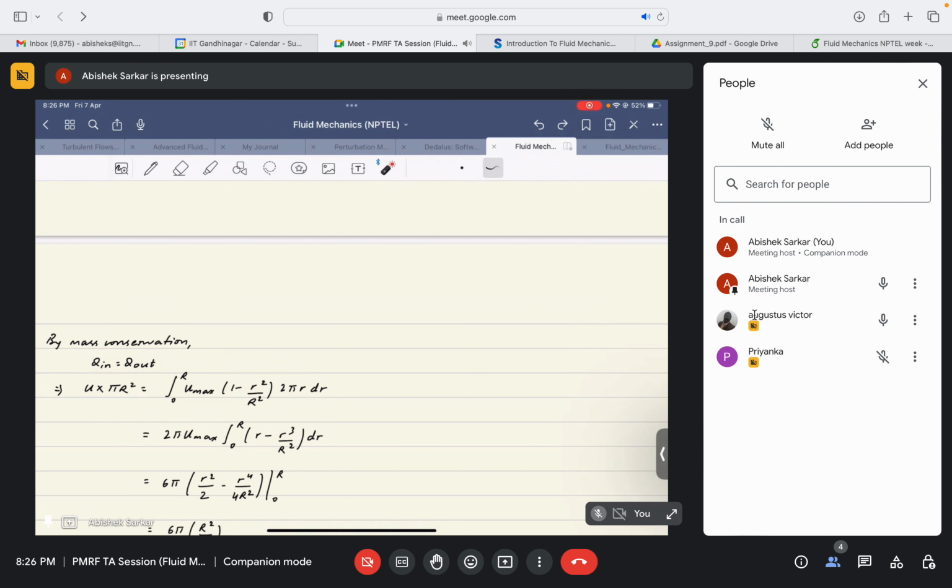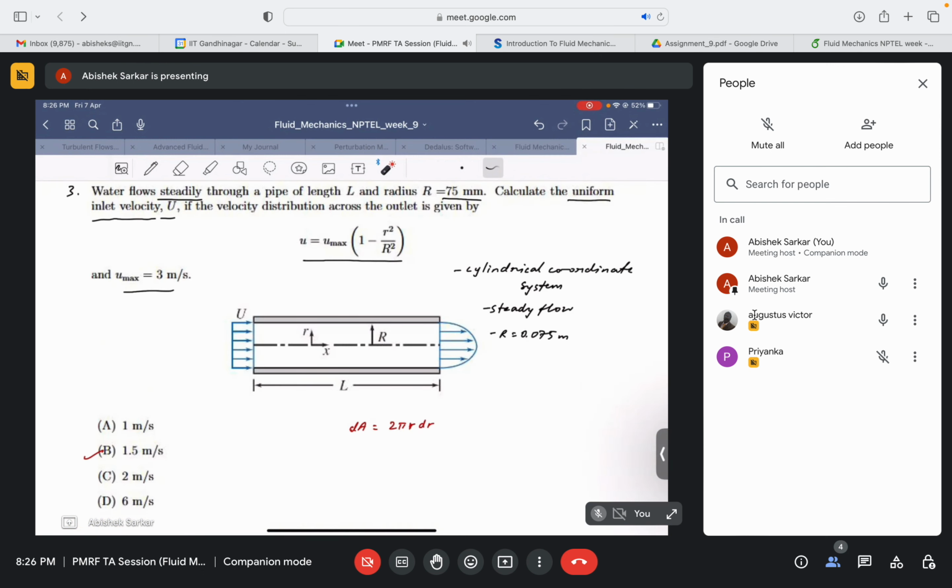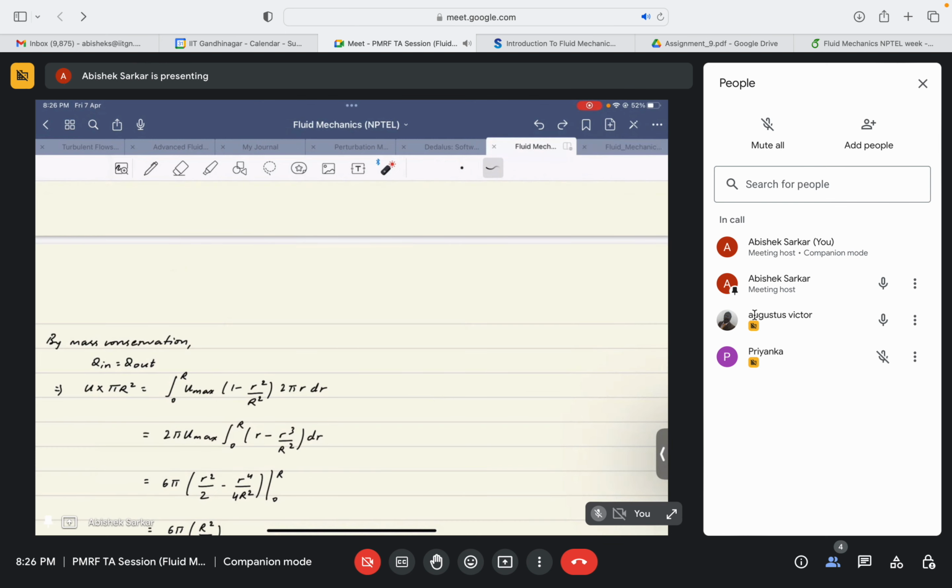changing, and you should also know that appreciable density change only takes place in a compressible flow regime. Since flow through pipes is generally incompressible, density essentially remains constant in this case. And if they mention water, it essentially remains constant. Okay, so density remains constant. Keeping that idea in mind, we can get Q in is equal to Q out.